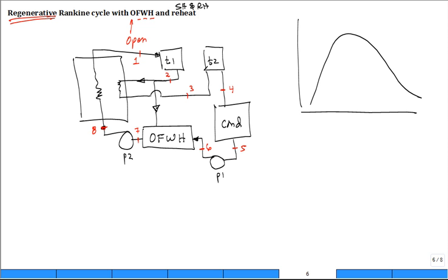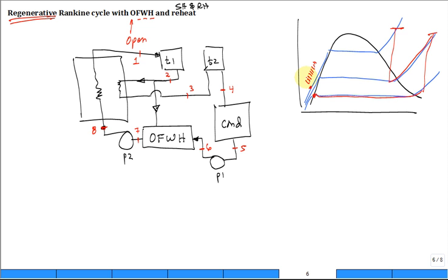Okay, let's put our line of constant pressure high, another line of constant pressure intermediate, and a line of constant pressure low. And somehow, because of temperature limits, we've taken that to the limit there, okay? So we're going to bring it down and then do that, and then bring it down and then condense. And now, if we just condensed and put it up to this high pressure, all of this heating would be used to heat up the cold feed water. And our goal is to get the feed water hotter without burning coal to do it, our expensive fuel source.